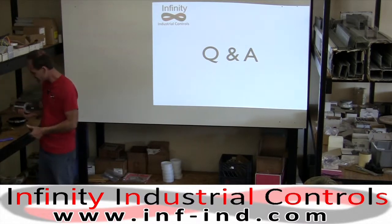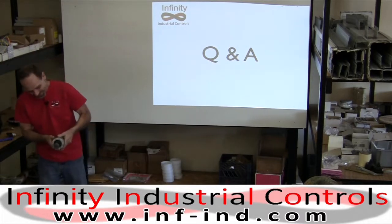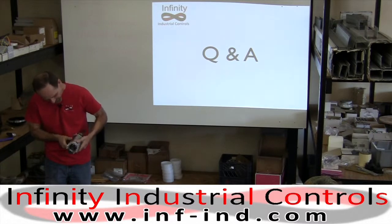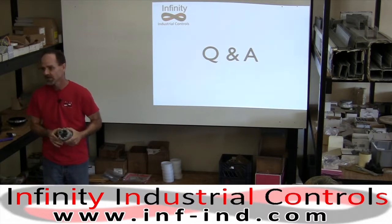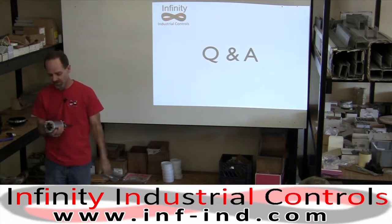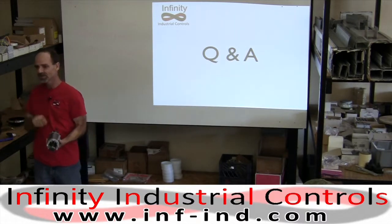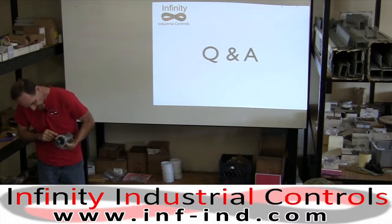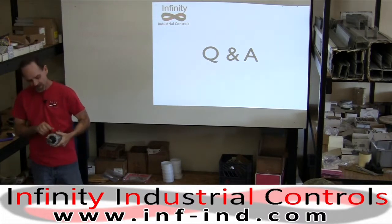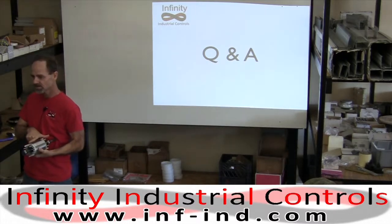Now this isn't a very good example. Usually you can see the poles in here, but they got this one shielded. This actually has individual conductors through it. Now, the way an AC motor develops torque is that rotating magnetic field in that stator that drags it around. Each one of these conductors, when a magnetic field crosses a conductor, it induces a current into it.